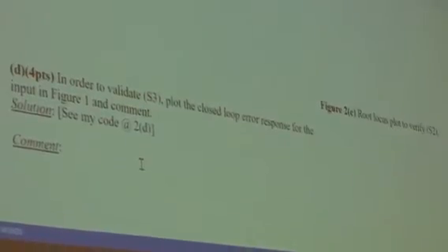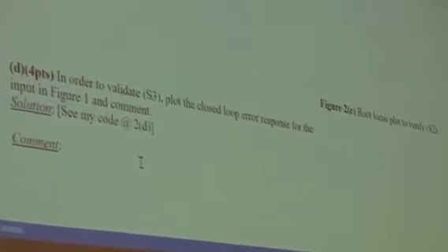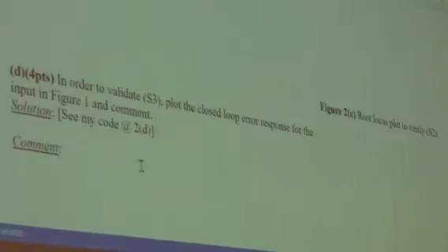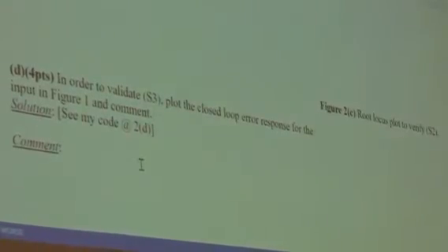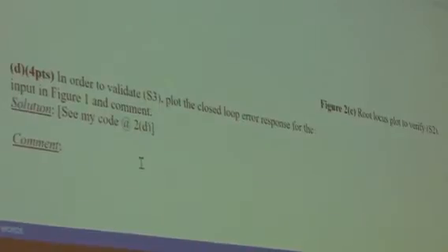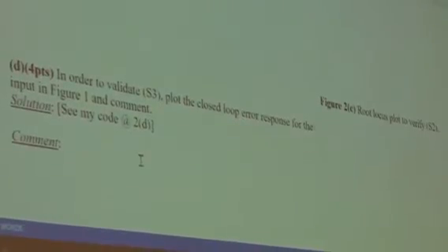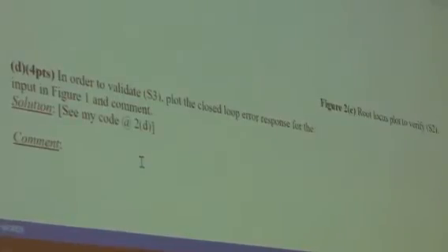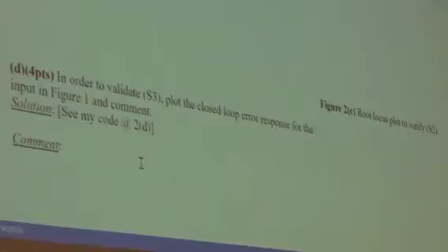So you can go back and say, well, obviously I must have used the open loop. That's the most common mistake people make, is they grab the open loop, but this is a feedback. It's closed loop feedback with a controller in there. So that's one mistake that might be occurring, is that you use the open instead of the closed. Another could be a simple numerical computation error, so you can go back and check and find out what you did.